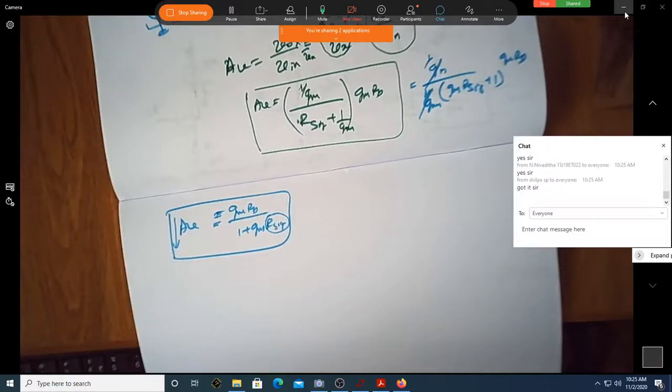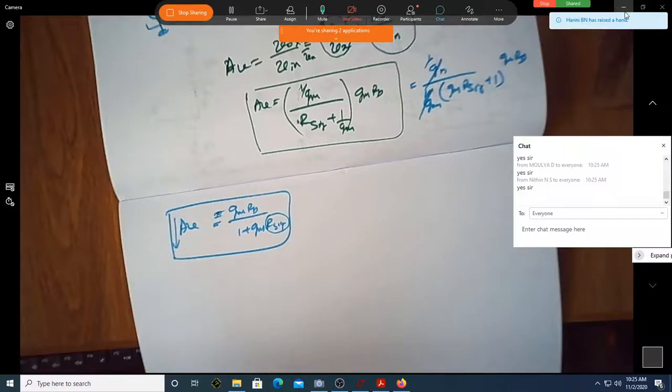The source resistance acting as a degeneration resistance? It is not exactly like degeneration, because in case of degeneration, the signal was applied at the gate. Actually, the R signal will reduce the amount of voltage that is going to the amplifier.